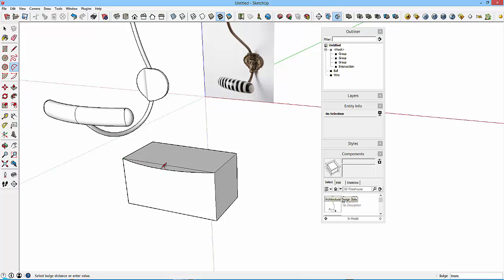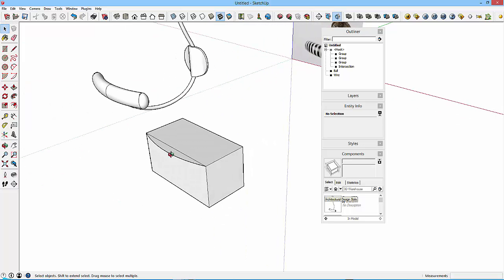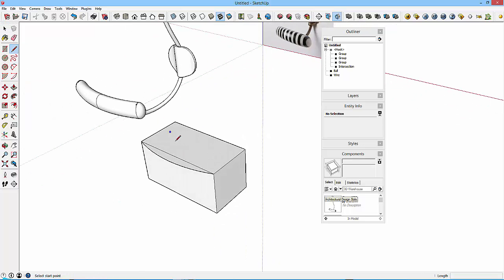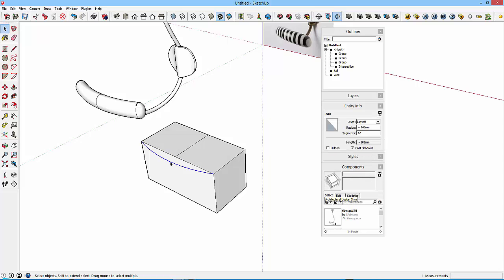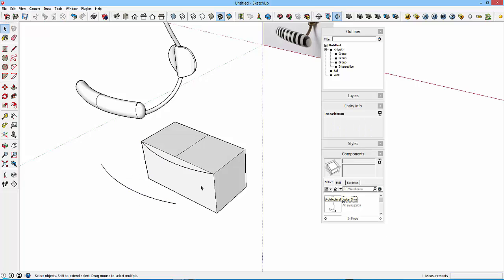That'll do, probably about 9 mil, that's fine. And I need to remember where the midpoint is, so I'll mark up the midpoint on that, even though it's highlighted by a snap point. Then I'll take a copy of this and pull that out, 50 mil. It's always worthwhile putting things in known distances, just in case you need to move them back or copy something from something else to it.